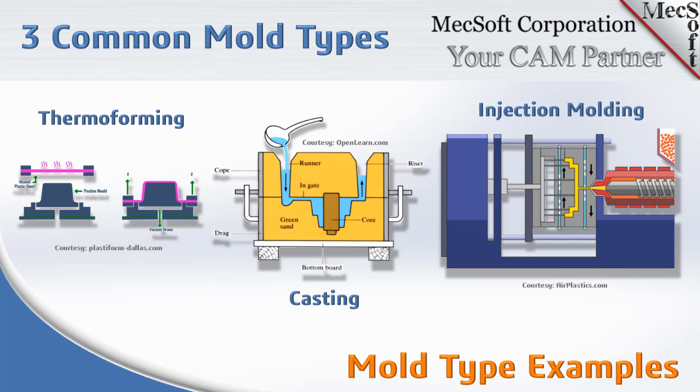And on the right, obviously, we're going to be spending most of our time on plastic injection molding. Just as an overview, in plastic injection molding, you're using cores and cavities and injecting various plastics, ABS, polypropylene, many different types of plastics under very high pressure into these cavities. So we're going to be talking about the core.